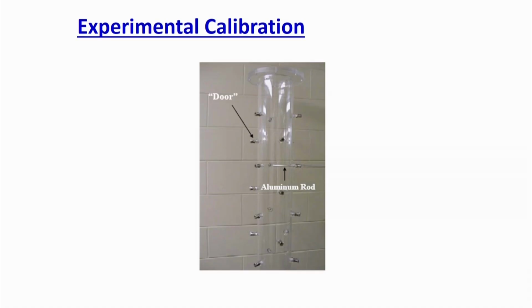Now how can we put the tracer particle? There are several ways, and if you go and see the literature on radioactive particle tracking, you will see that everyone devises a calibration device based on their column operating condition, column geometry and column size. What we are going to discuss is one method which is very simple, and we always use that in our laboratories. Now the first question you can ask is, why in situ calibration?